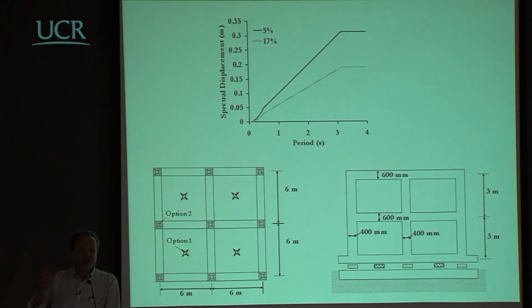So if you want to have a certain value of period of vibration that comes out from your spectrum, you may end up being not able to do that, because the vertical action will maybe be too low, and you have to use certain size of the isolator.